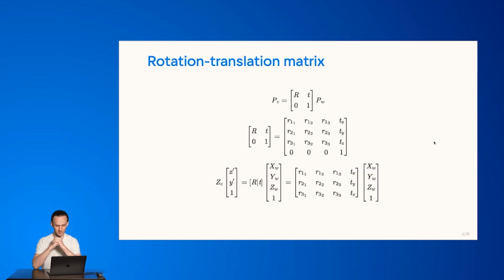Here we can dive just a bit into the details of the application of this rotation translation matrix. We can represent the rotation, as you know, by a 3x3 matrix in 3-dimensional space. And the translation could be represented by a single vector 3x1. And so-called homogeneous coordinates make it possible to accommodate all of that into one single matrix, so that bringing some vector into another reference frame works by just multiplying this vector by a single matrix. That is very handy, useful, and convenient.